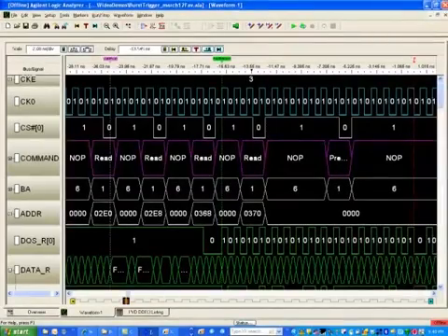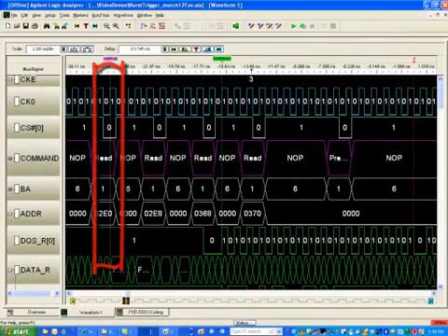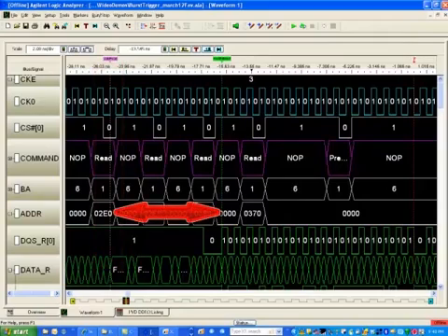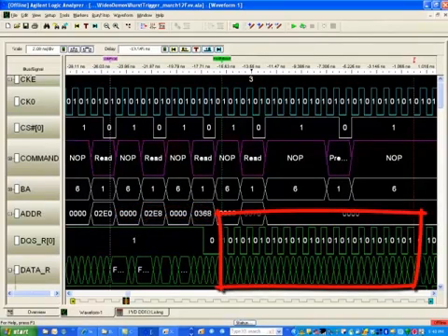Opening the state waveform window, on our left-hand side, we have the first valid read request. Then there's the CAS latency until the burst actually begins. That first read burst is immediately followed by a second, a third, and the fourth read burst. At the end of the fourth burst of data, the trigger has seen the last pattern, all 32 exact data